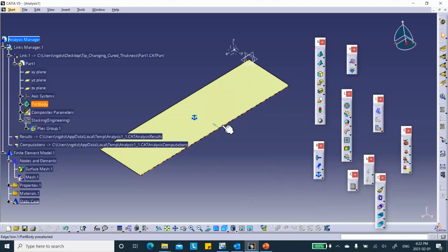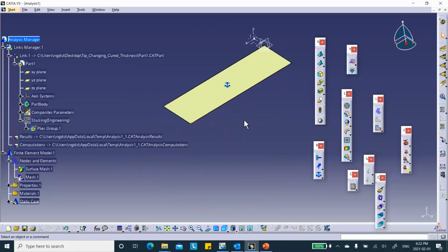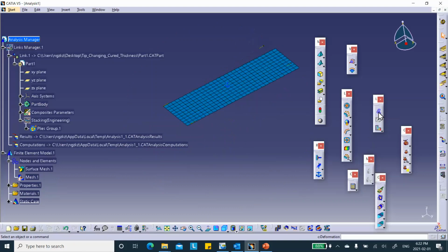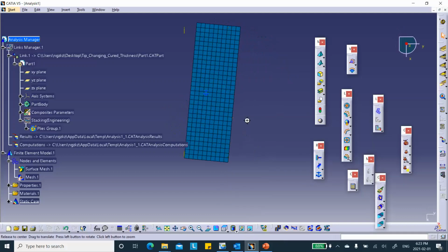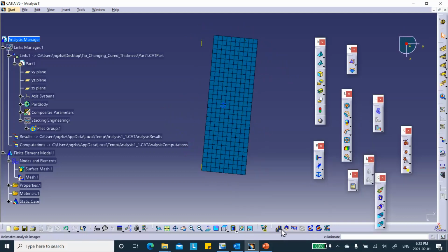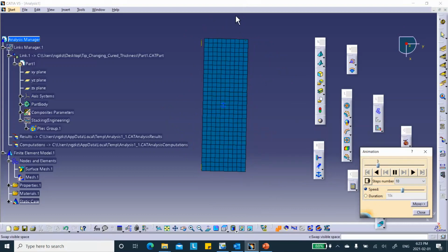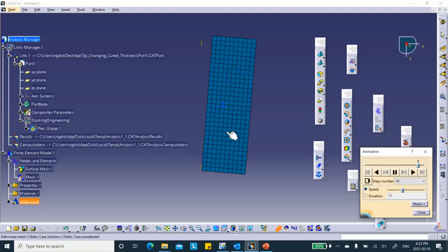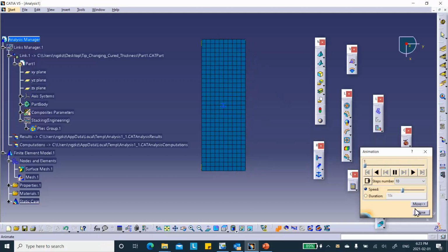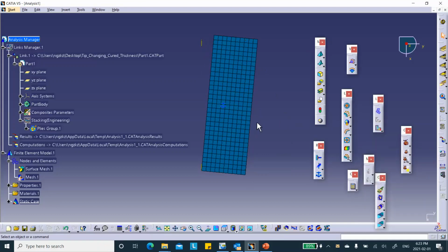Okay, done. Now, don't let this thing scare you, because if I say show me the deformation, and you look at the view from the top, you may get the impression that this is shearing, but it's not shearing. Look, 90-degree angles. See, the 90-degree angles remained at 90 degrees. This is a stretching in that direction, but it's not shearing. Of course, if the angle was not 0, it would shear, but not here. Okay, so how do we check our results?